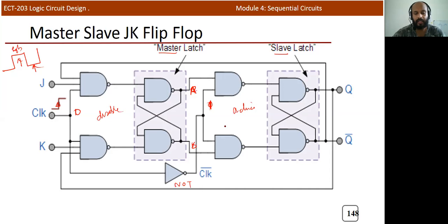So the already latched value A and B will be fed into this particular slave latch, and the corresponding output you will get at the output side. In this case also the output is fed back to the input side, but at this instant the first, master latch is disabled, because the master will operate in high and the slave will be active only in the low state.